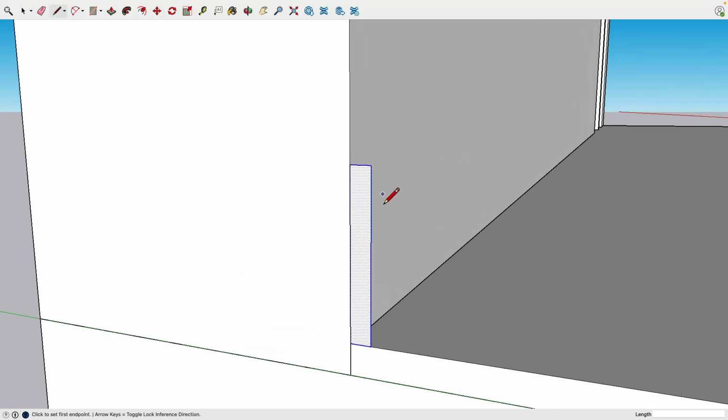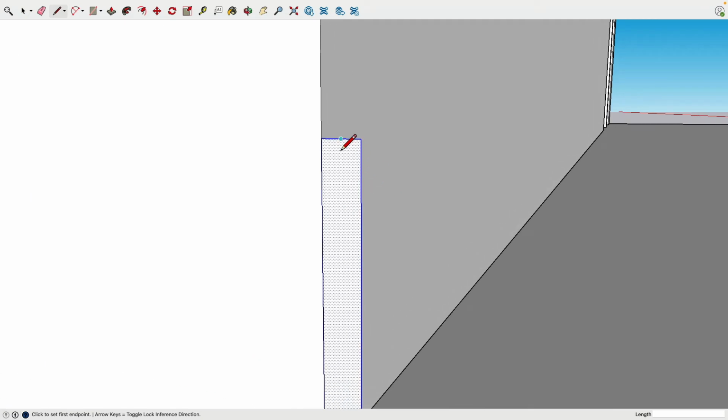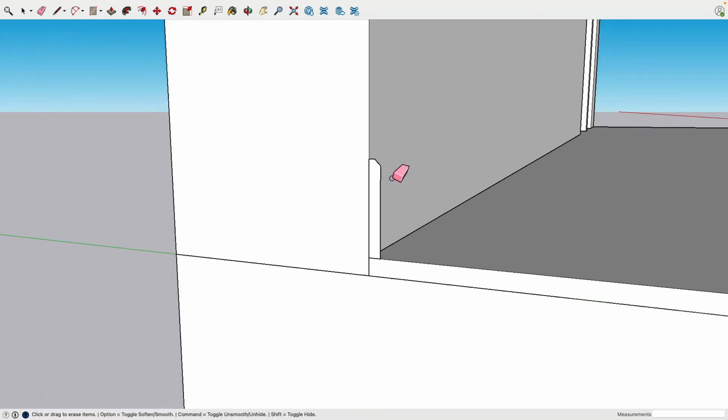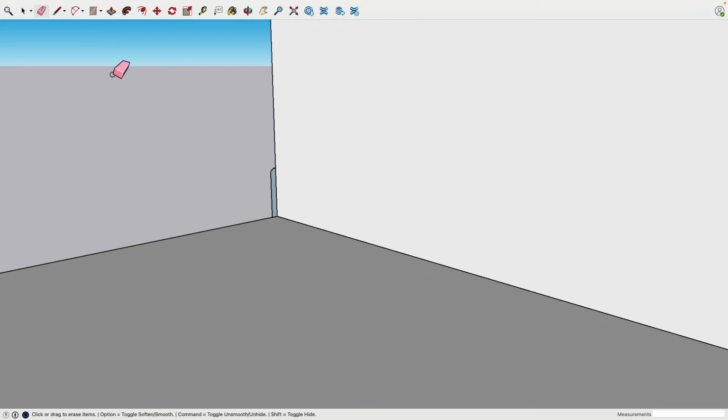See, easy peasy. The corner here we would like to chamfer. So I draw from the midpoint a vertical line down. Very easy drafting. Rotate this line 45 degrees. And then with the eraser, I get rid of the rest. There we are. Pretty nice. Cool.